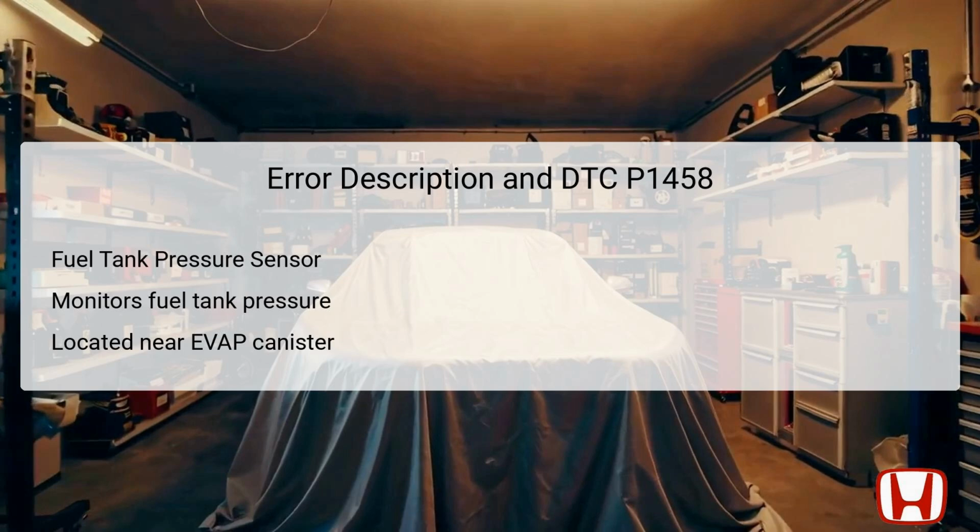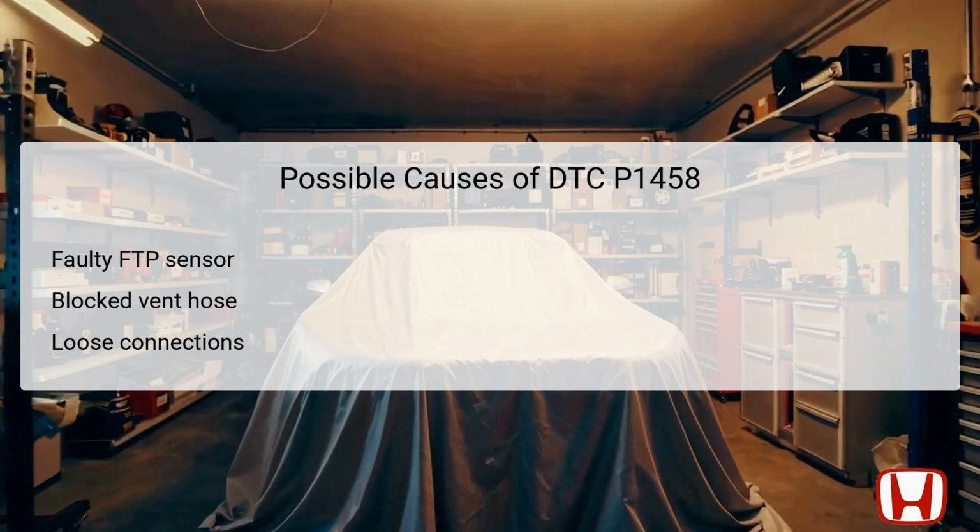Proper operation of the FTP sensor is critical in ensuring that fuel evaporates correctly and that the emissions system functions as designed. The sensor values can fluctuate during operation, and discrepancies can result in detection of DTC P1458, potentially affecting the vehicle's overall emissions performance. Thus, identifying any issues with the FTP sensor is crucial for compliance with environmental standards and to assure the vehicle's efficient operation. Several possible causes may lead to the DTC P1458 being triggered.